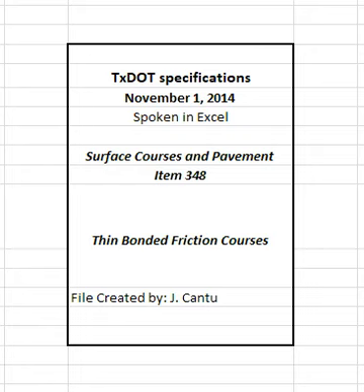4.9.7 Irregularities. Identify and correct irregularities including segregation, rutting, raveling, flushing, fat spots, mat slippage, irregular color, irregular texture, roller marks, tears, gouges, streaks, uncoated aggregate particles, or broken aggregate particles. The engineer may also identify irregularities, and in such cases, the engineer will promptly notify the contractor.